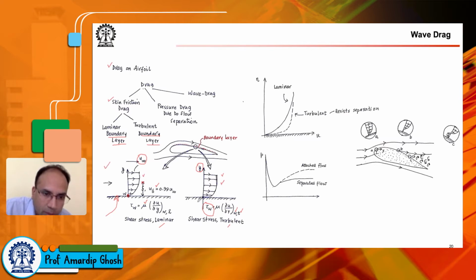Once again, we have not talked about boundary layer in detail, but it is a thin region near the wall of these bodies immersed in flowing fluid, where these velocity gradients exist. In fact, beyond this thin region, the flow behaves almost like an inviscid flow field. So although there is viscosity, velocity gradients are not so severe, and you can apply inviscid flow field analysis to regions outside the boundary layer.